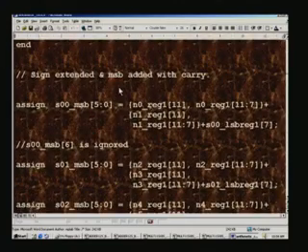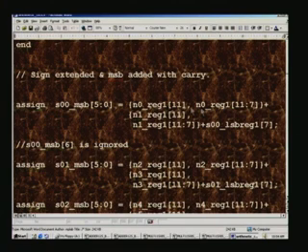Before we add the MSB, we should not forget to extend the sign, and this extension of the sign is merely duplication of the MSB. This is MSB 11 through 7, and this is the sign bit. So we just duplicate it here, and the whole thing is a concatenation. That means we first write the duplicated sign bit here of this number called N0 reg 1, that is registered at clock 1, and the whole thing put together is a sign extension of the MSB.